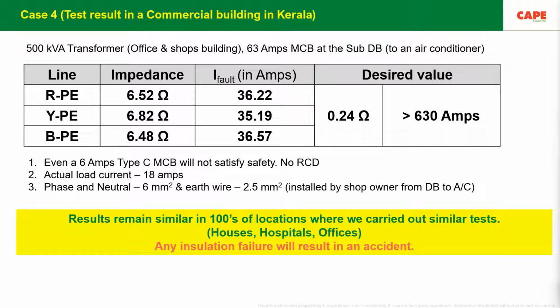And this name is written in IS 3043 in 66 places, with its definitions and applications. In IS 732, in about 62 places, fault loop impedance, disconnection times and disconnection methods are explained. But this is unknown to the user. Of course, he is not an electrical engineer, but it is unknown to the contractor and unknown to the designer. This is the pathetic situation.